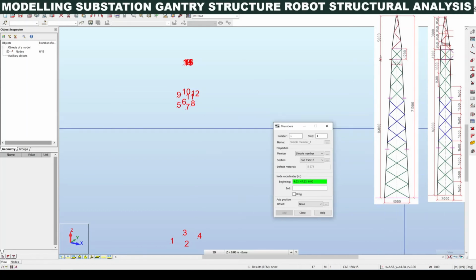You can see here, because in any of the tower section which is having more than 6 meter or 12 meter, we need to check with the steel fabricator whether they are having the available length of angle sections. Generally that angle section used to have 6 meter minimum or 12 meter as a maximum with the steel supplier. So we need to check out that if they don't have more than 6 meter, we have to make our entire length of the main leg into splices, which is to be limited to 6 meter.